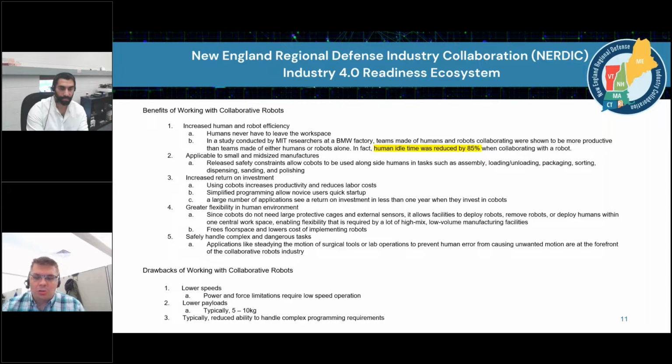Most of these robots are relatively small. They don't require three-phase power. They don't require the extensive safety setups that you needed before. So it makes them very easy to deploy and to redeploy. For instance, the cobot that we have here plugs into a standard wall outlet and is on a mobile cart that we can move around. You set it up to tend a machine for a shift and let it run, and then you come back in, say, the next day and say, oh, I don't need it to tend this machine anymore. I want to take it somewhere else. You just shut it down, unplug it, roll it over to the next machine, set it up, and have it run on another machine. It's very quick and easy to do that with a minimal amount of effort.